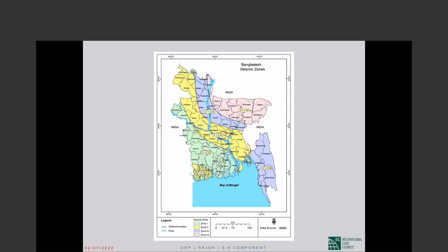Any detailing from collector to shear wall? Certainly, detailing requirement for collector to shear wall. So it's just a general question. Are you going to go over that detailing? I don't know that there is any specific detailing requirement for collectors. We have to have the reinforcement that is needed, and then the overstrength factor on the connection. But there is no special detailing requirement that I'm aware of.